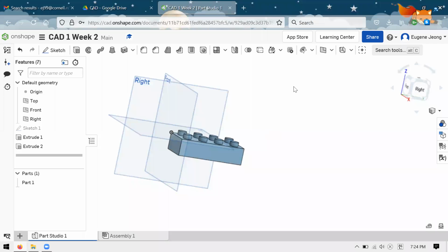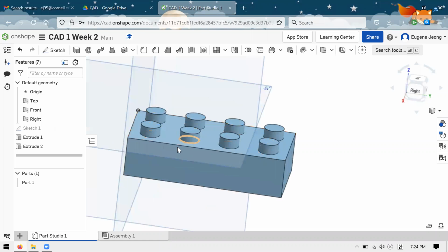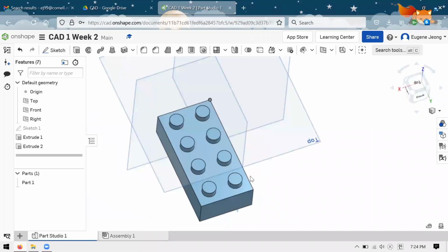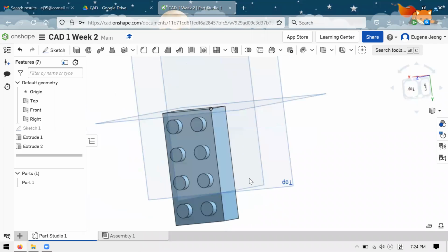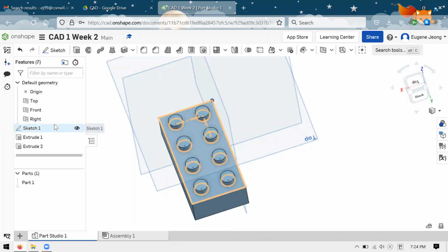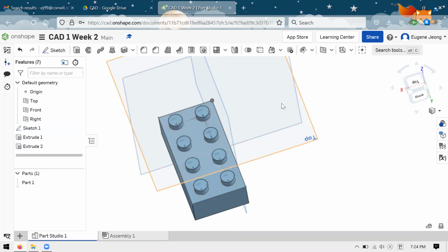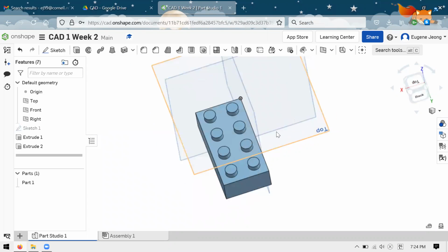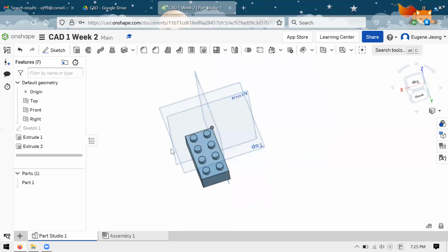All right, here we go then. You'll notice at the bottom here, it's blocked off. It's a solid piece, and that's not really very helpful. Oh, I see something. How do I not show the lines? The lines come from your sketch, which is presumably shown. So you can hide it by clicking the eyeball in the feature tree, just hover over it, and you click it, and hopefully the lines will disappear.